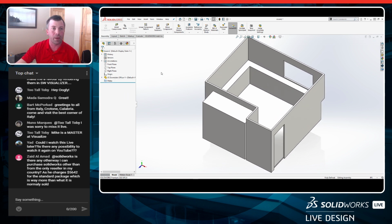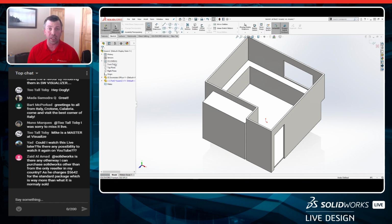So once we have that, I'm going to go ahead and insert a new part to it. And this is going to be my desk. Now, same thing. We'll go ahead and click the new part. And instead of clicking anywhere in place, I'm just going to reference the front plane. And what this will do is, again, establish that same coordinate location. So the new part has the same coordinate location as the assembly, which is the same as the room. So we're all in the same central space, and I don't have to worry about mating these up or anything. Everything will kind of unfold.